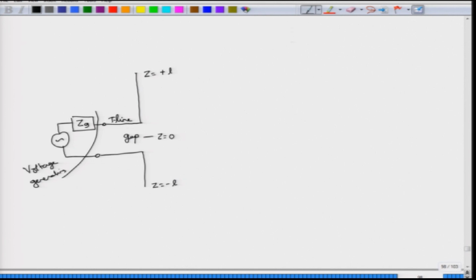Okay. And because of this current which is varying with respect to time, you will have this A field, that is vector potential, and by calculating the vector potential you can then calculate what would be the electric field and the magnetic fields of this antenna as radiated away, right. So, that is where we would like to go.